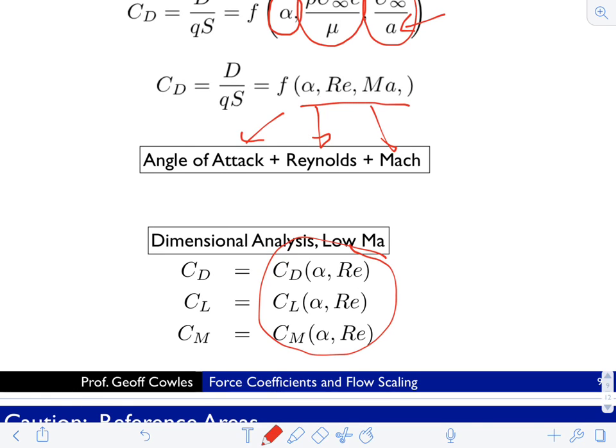When it comes to lift, the Reynolds number is really not as important, particularly at low angles of attack. What's driving that lift is the pressure distribution. What's driving that pressure distribution is the shape of the wing and the angle of attack. And you're going to control those. And you might have the Reynolds number wrong, but it's not going to really mess too much with your pressure distribution unless you're near stall, or unless you're at extremely different Reynolds numbers.